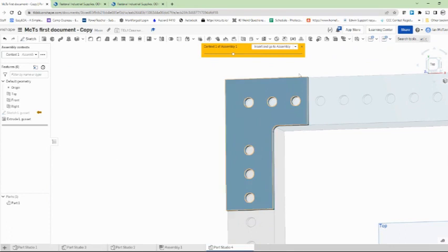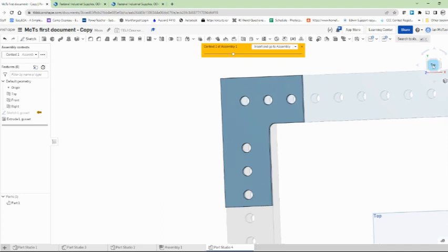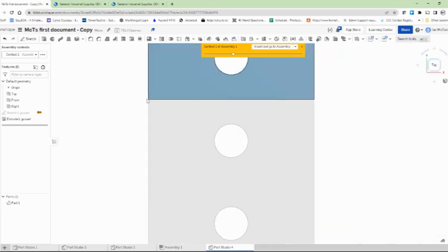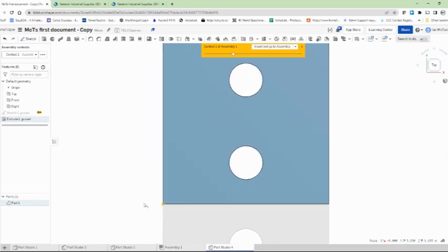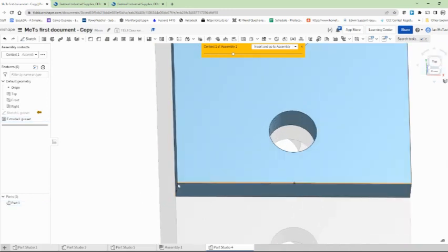That's great. Now, the other thing that we talked about in class is, if you look at a ship or an airplane, the windows are always curved. And the reason for that is, right now, if I had a force on that, everything gets concentrated on that one point, which could lead to a failure point. So by curving the edges here, that allows you to distribute the force, instead of having this sharp point where if it gets banged, it gets damaged. It distributes the force more. And we are going to do that.